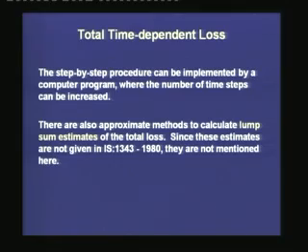Several such programs are being written and they are available commercially, and this can be used by the users of the precast or the prestressed industry, and it has to be checked which code they are following and which procedure they are following, and after that these programs can be used to have a more detailed calculation of the losses due to creep, shrinkage and relaxation, and to monitor the pre-stressing force with time.